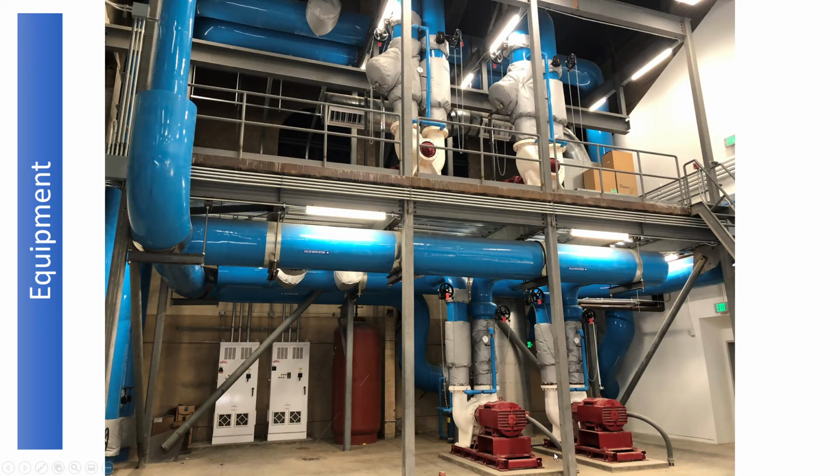So this is the pump that we just looked at. This is our 100 horsepower motor. These guys upstairs are 150 horsepower, I think. But what I want to show you in this picture is that these devices over here in the corner are called variable frequency drives. And this is the electrical piece of equipment that's actually controlling the speed of these pumps. A variable frequency drive, you'll hear it called a VFD. You might also hear it called a VSD, variable speed drive, essentially the same thing, controlling the speed of the pump. And if we control the speed of the pump, then we're meeting load and we're reducing energy use on the whole system.